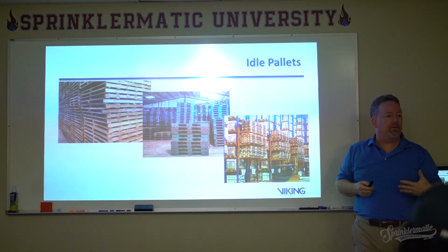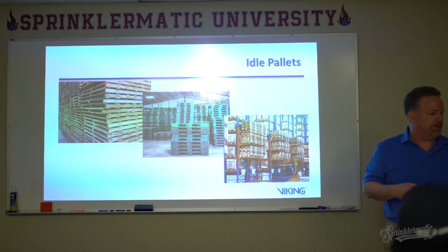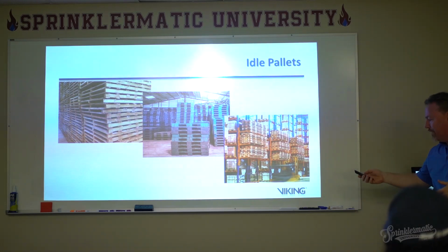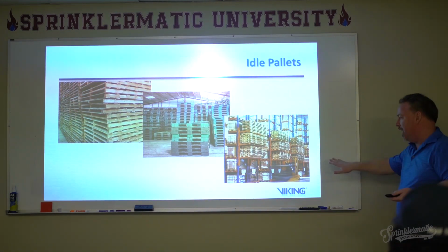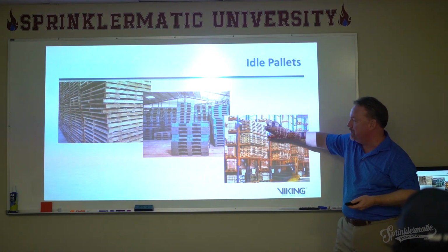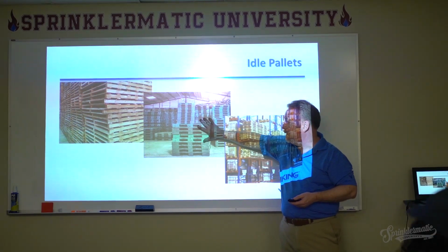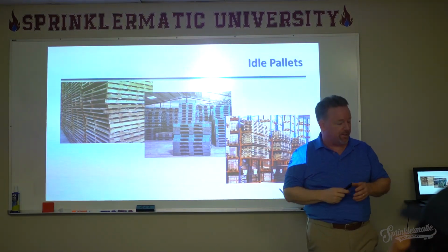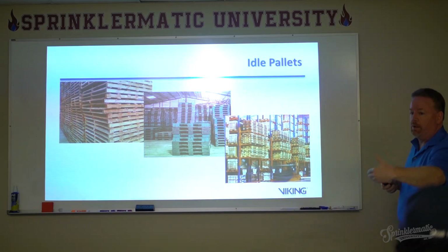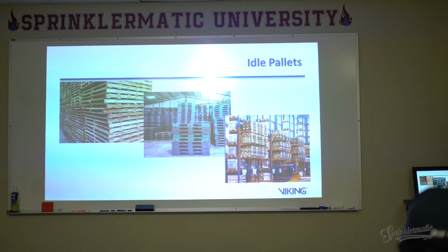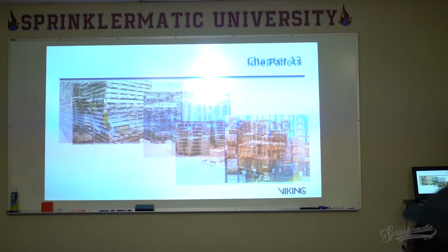I will tell you though, if you wind up with idle pallets being stored inside, either attached to the racks or inside a building, here's some plastic pallets over there, or some wood pallets there, NFPA 13 Chapter 12 does have specific guidance on protecting inside. And the best thing that they say about protecting inside, as I said before, is get them outside. Don't store them inside.